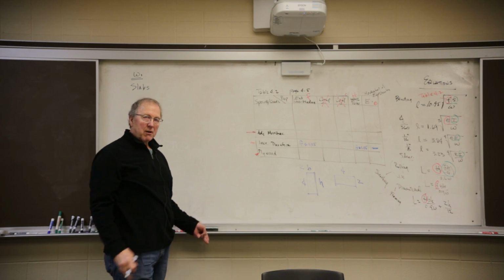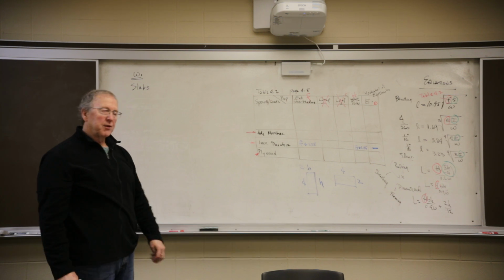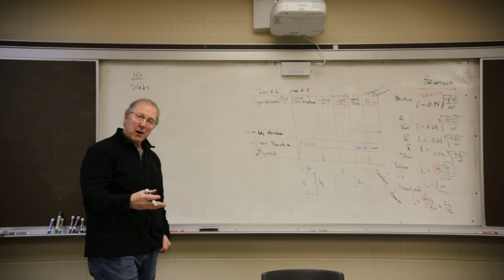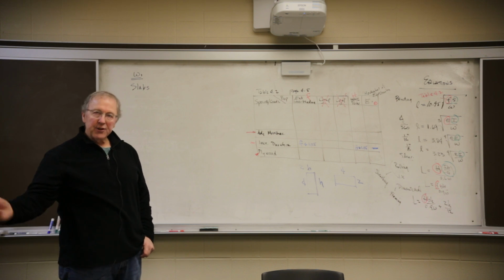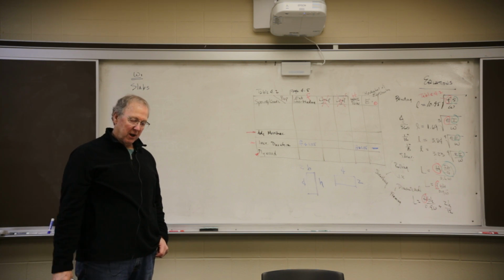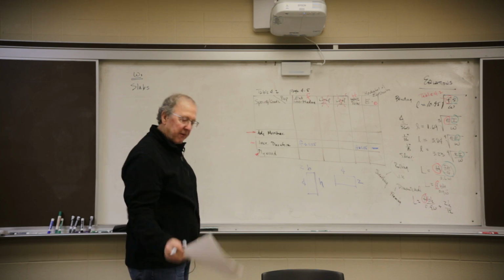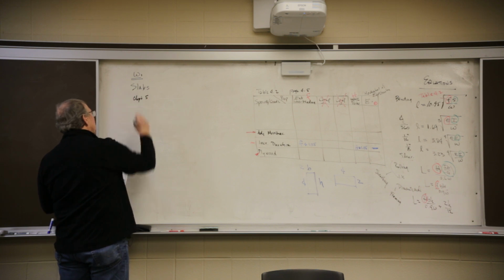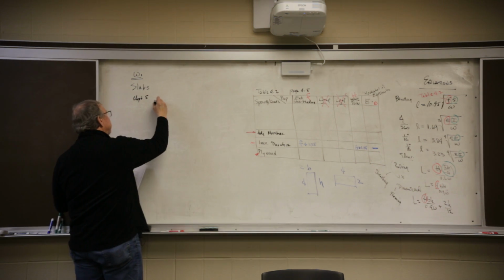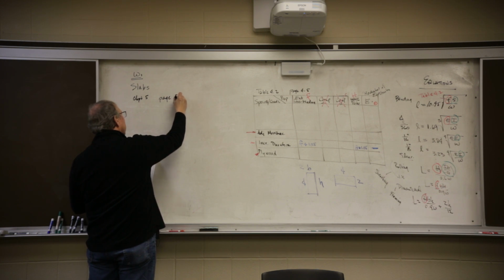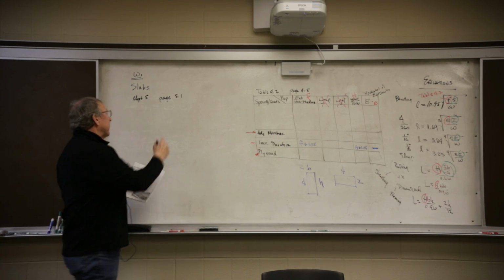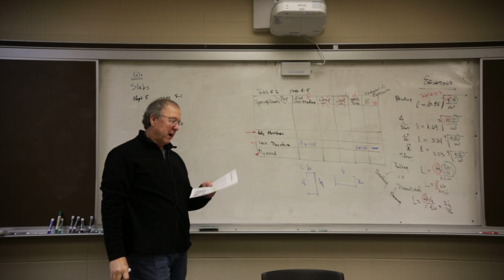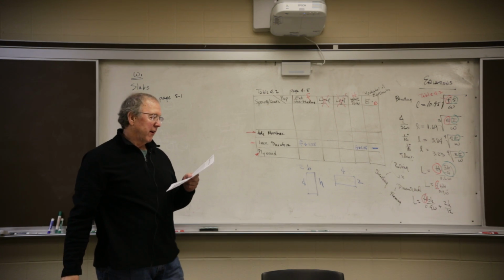Now I said it's going to float. It's going to change from member to member to member. The W is going to change. So for sheathing, it's 1. For studs, it's another W. For whalers, it's another W. So it's going to keep changing on us. So where do you find it? For slabs, it's chapter 5. And it's on page 5-1. Okay? So it's on 5, and if you've got the handout, the part that's shaded, it's on the right-hand column, just about at the very end.